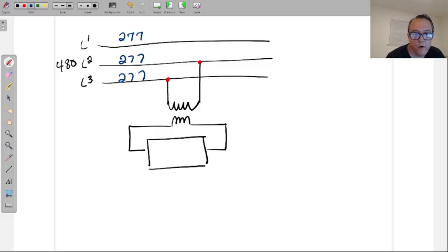So I have 480 coming in to a transformer, converting the voltage or stepping it down to 120 volts on the secondary side. Here we do use primary secondary for those who haven't done transformers. And then 120 volts. Here we've created an L1 and an L2, just like the ones that I've been showing you on the diagrams. But those L1s and L2 are not going to the control circuit yet. They're going right into the power supply, hot, neutral, hot, neutral.